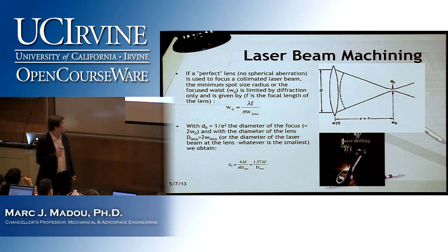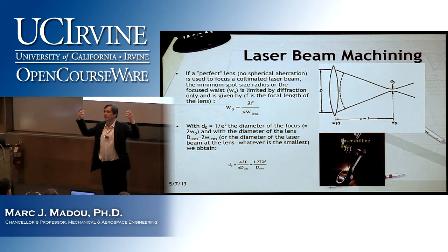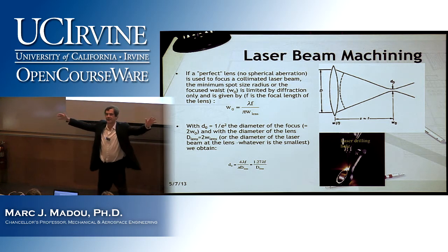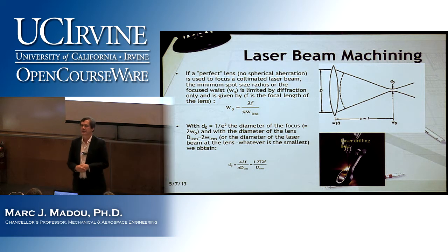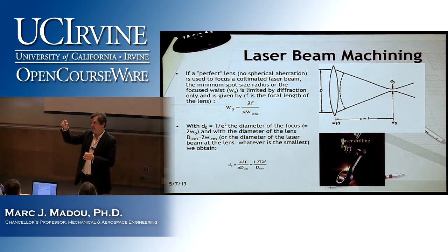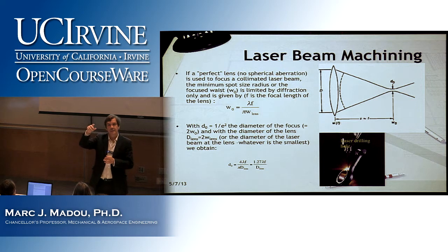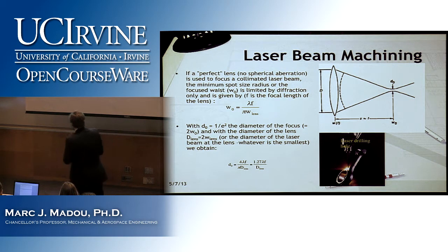What is in it? And it should be very familiar. Without looking at it, what was the resolution in photolithography? Of course, I can't hide it, right? But what was R, the resolution in photolithography? What went in there? It's a good preparation for Thursday. So R in photolithography equals K, a constant, and then? Very good. Wavelength over numerical aperture. And look what we see here.